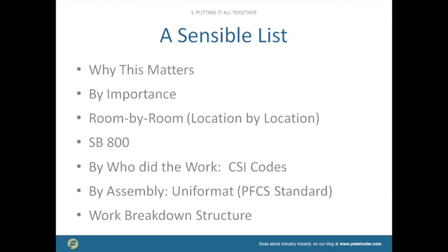But the plaster in the shower is in a completely different section because it's by construction assembly, and the top-level summary is substructure, superstructure, exterior cladding, then interiors. So the shower is going to be in the interior section in Uniformat,